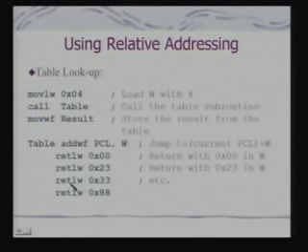What is the instruction in the table? The table is represented as RETLW instructions. So, what does that mean? In this case, you return by loading a particular value onto W. So, a complete table lookup operation has been implemented, and implemented pretty efficiently with pretty high code density.